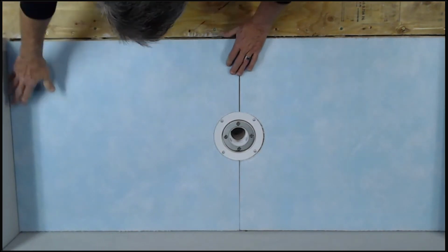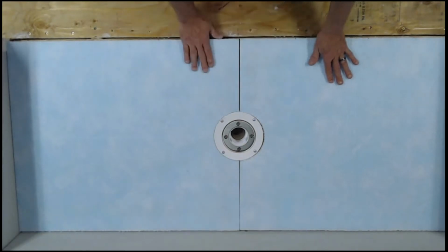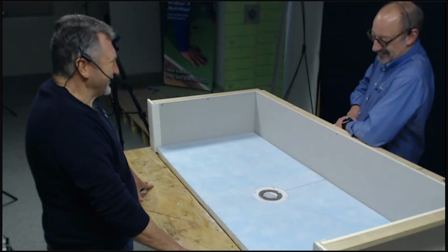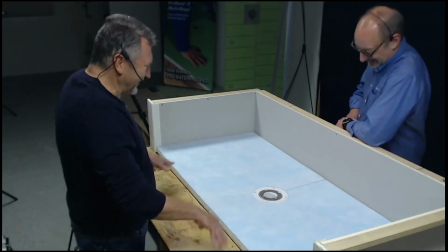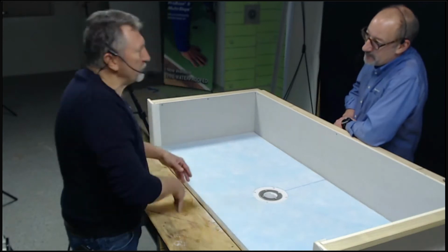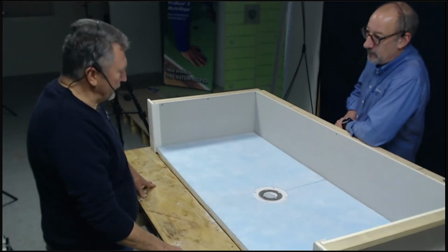That flushes out perfect. It all flushes out perfect to that drain. You would think you designed it around the drain. So this base will be bonded down to the substrate by using modified thin set, just any latex modified meeting the A118.4 standard.